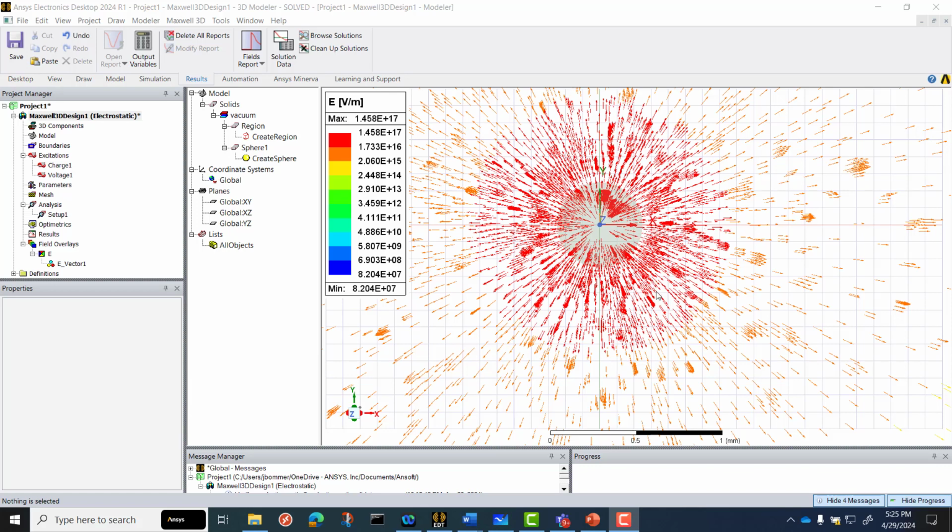So I would say a safe value to compare would be things that are taking place just outside the surface. If we compare our 1 millimeter distance from the center of that point charge, I would expect that to compare pretty favorably, within the accuracy settings of our computational solver, to the analytical estimate.